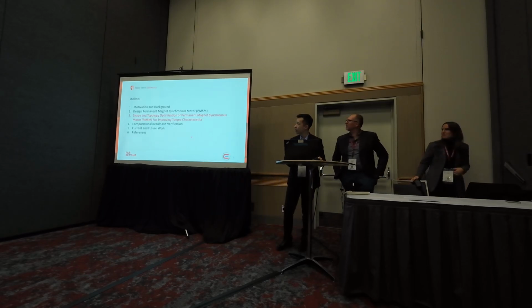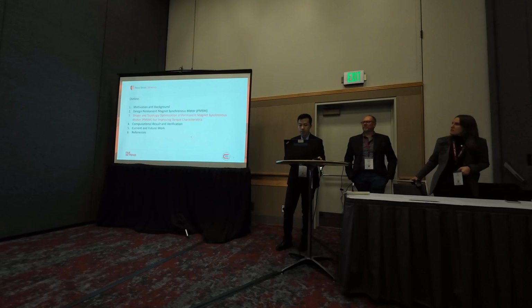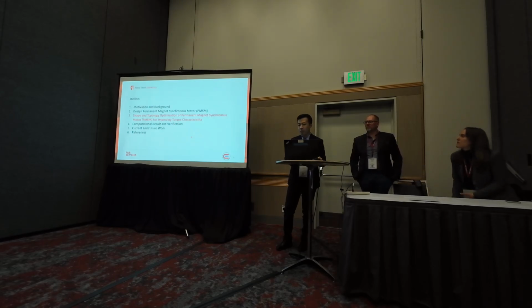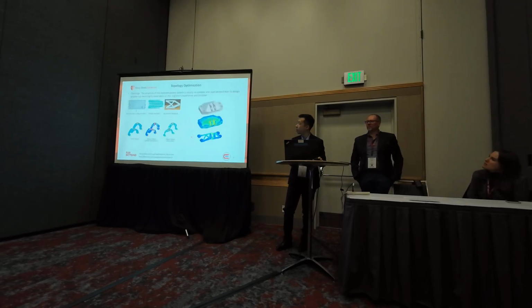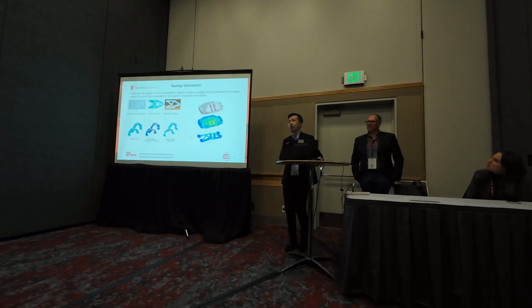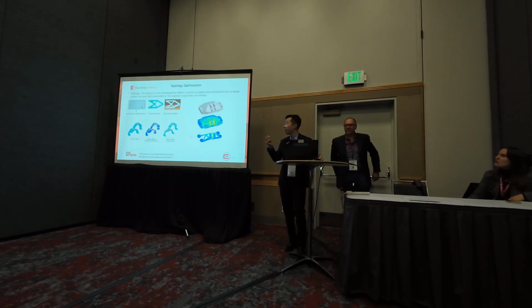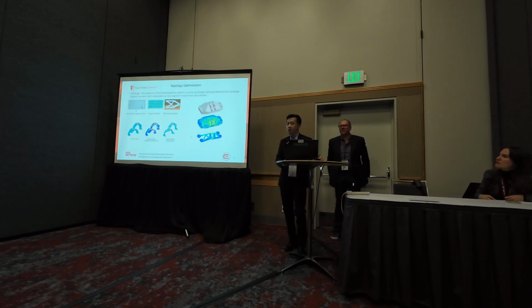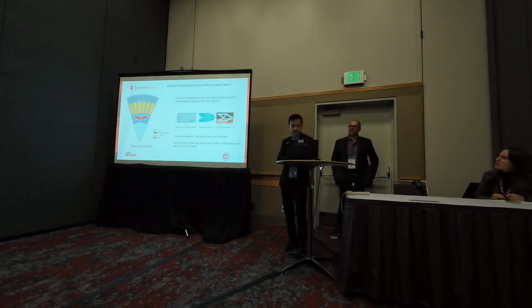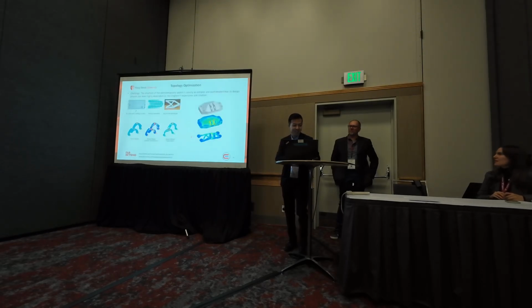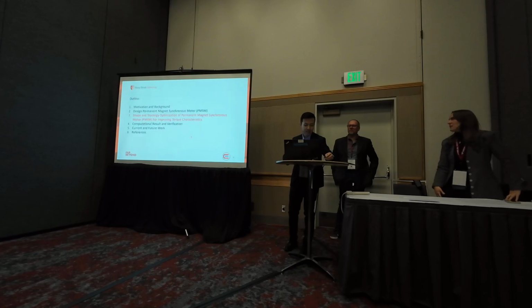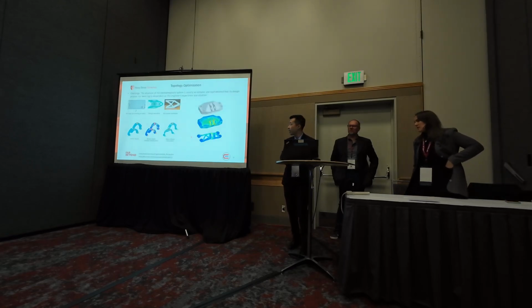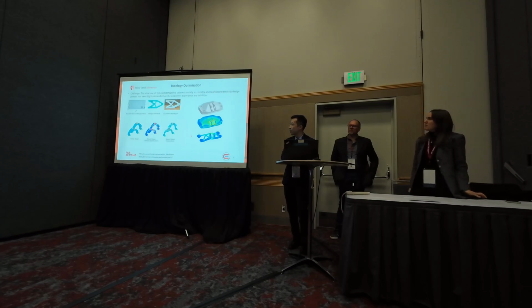So next step, I will focus on the shape and topology optimization of the permanent magnet synchronous motor for improving the torque characteristics. I believe most of you are very familiar with topology optimization, which is the numerical tool that optimizes basic material layout within a given design domain. The challenge is that the structure of the electromagnetic system is highly dependent on the designer's intuition and experience. So these are some classical examples of topology optimization.